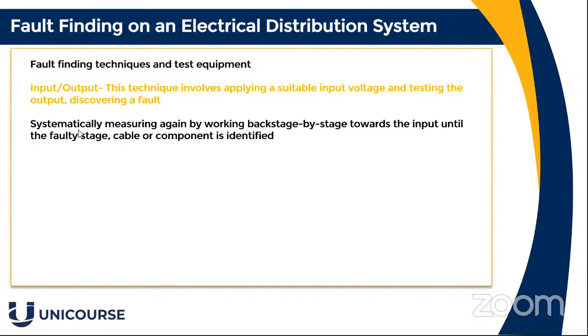So they have to work systematically, and that's important because of the safety aspect. You can't just work on these haphazardly. They have to carefully check each section to see where the supply is and where the supply is not there. And then from there, they can deduce where the fault is. And then they have to make decisions. Can they do a temporary repair? Can they repair it so it's permanent? Or will it require taking out? And then they need to have a standby, or have the distribution moved somewhere else, which gets very complicated.